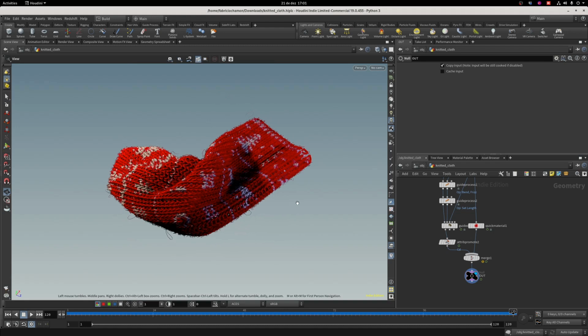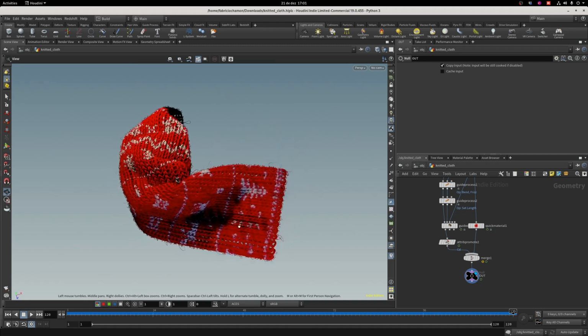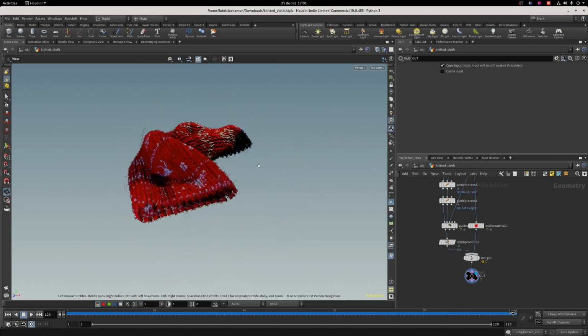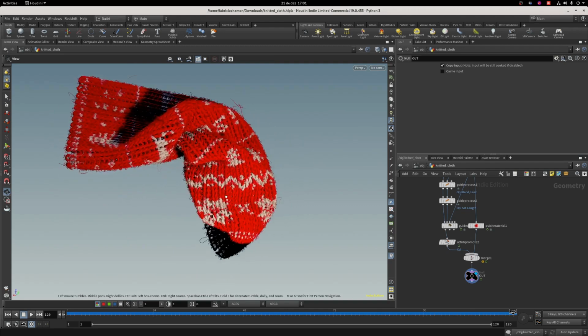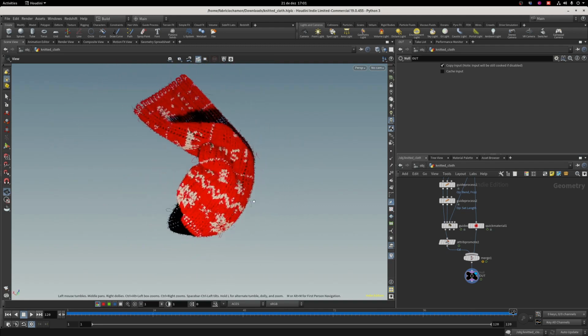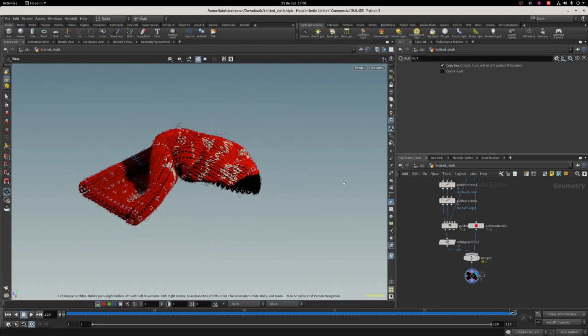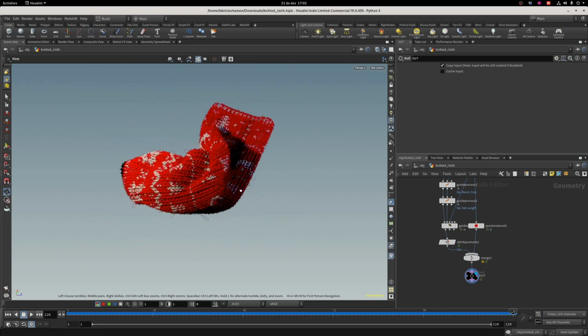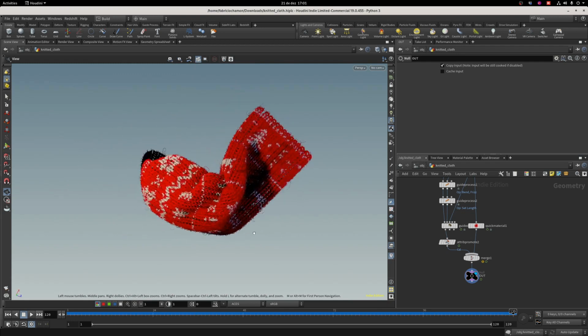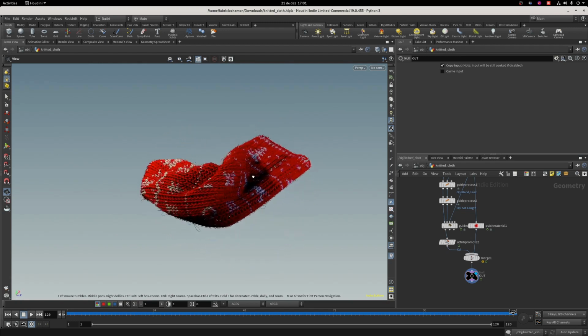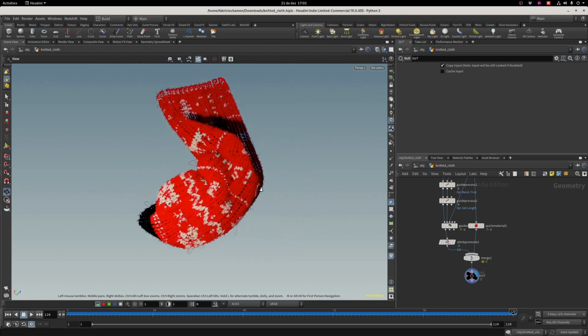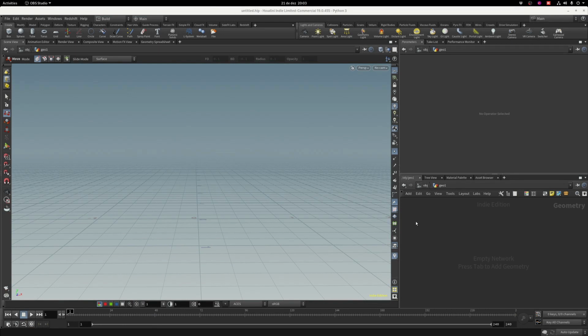Create some nice looking knitted fabric in Houdini. We'll explore some concepts like how to use uvsample to transfer a flat knitting pattern over to any UV object, and finally how to apply some fuzzy hairs on top for extra realism. So let's take a look. Alright, Houdini 19 here, empty geometry.